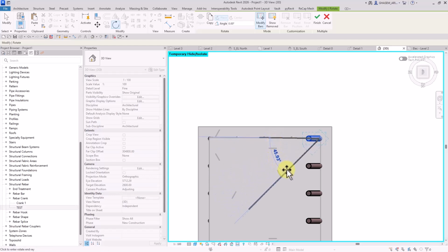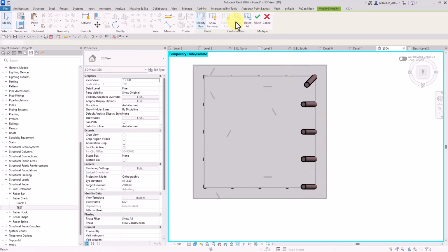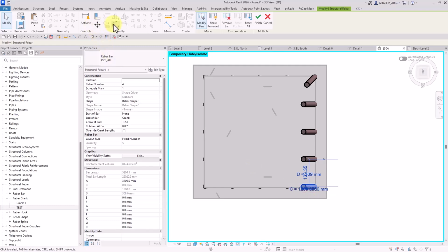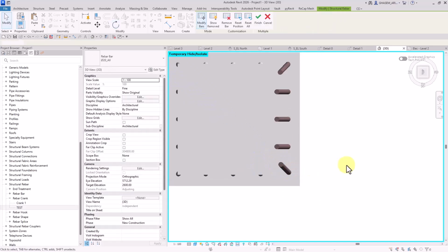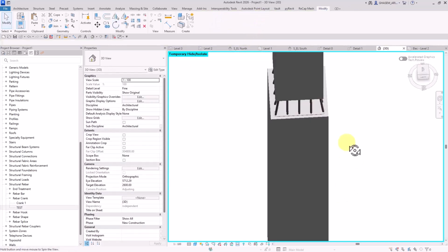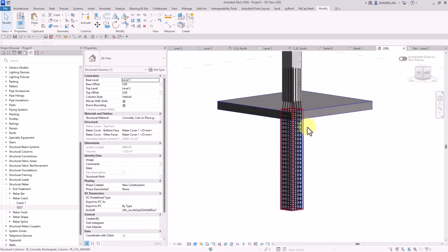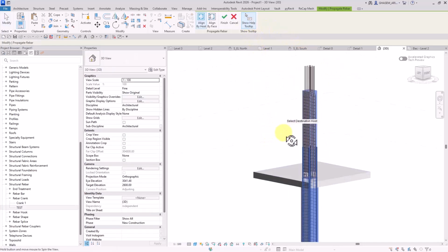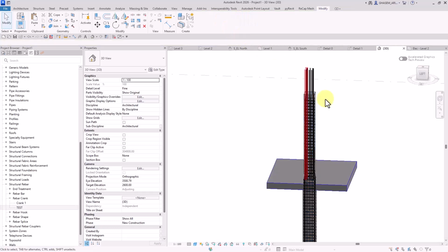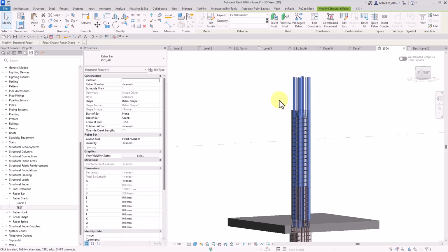Okay. We should do the same for the next one. Again, reset first. And again, rotate. From here by 45 degrees. Alright, it's finished. I guess this is correct now. I need to reproduce the rebar. I'm going to select this and use propagate rebar. And we would get the crank up here as well. And if we didn't want this up here, we can set it on none.